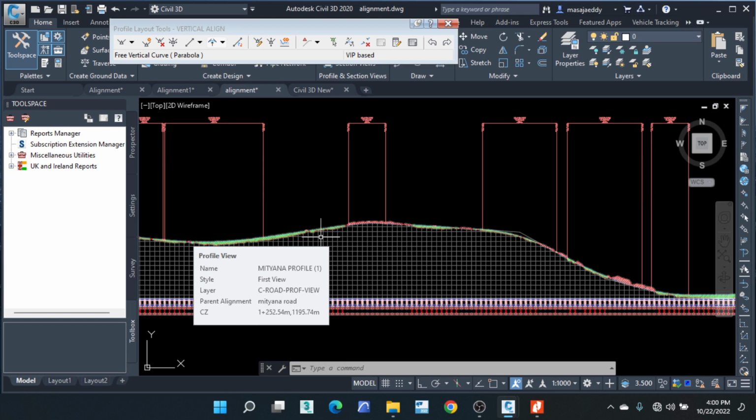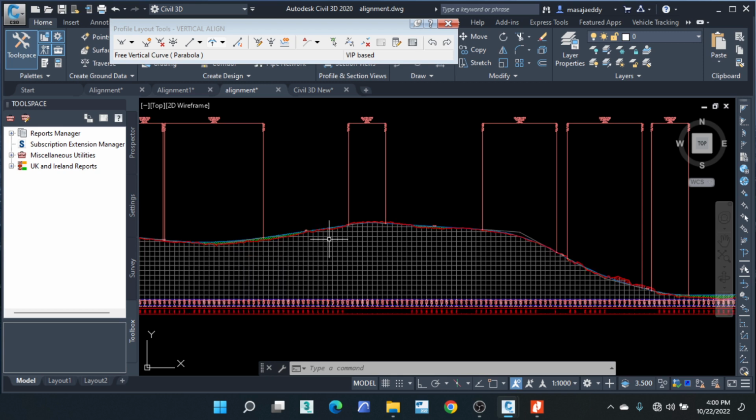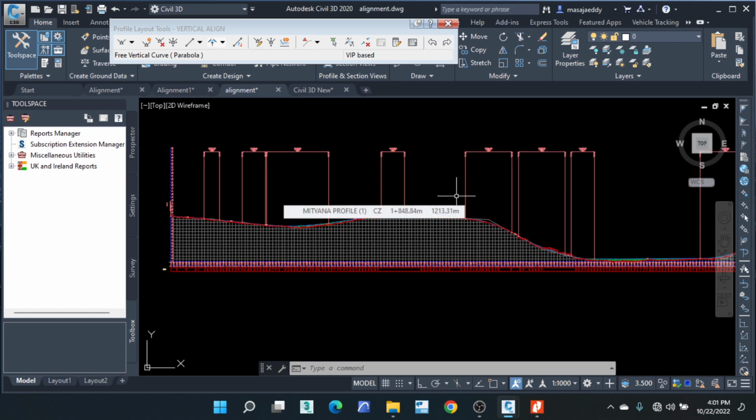If you can't achieve the minimum fill above the culvert, you encase the culvert, actually. That is for these round culverts. For a box culvert, if the fill is not enough, you make sure the top slab of the culvert is thick enough to accommodate the traffic loads. That is why we provide for fill.